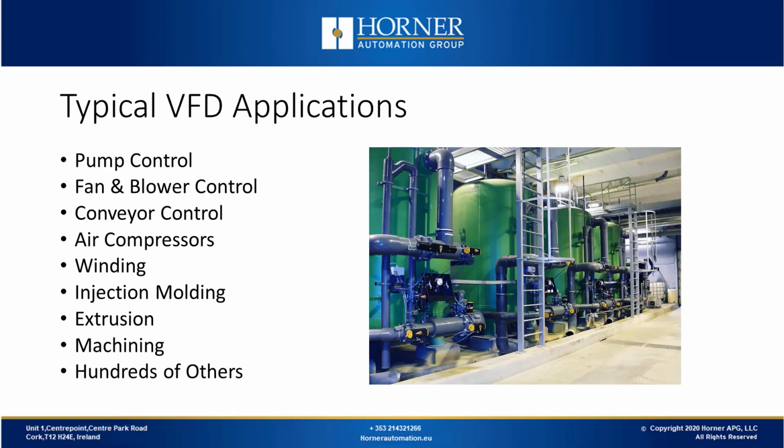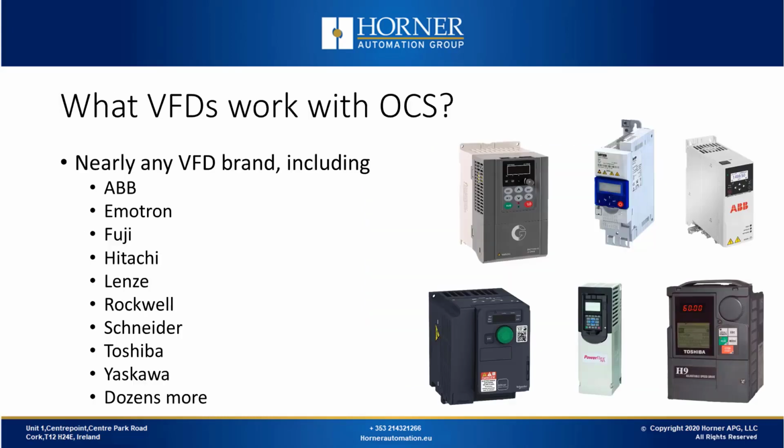Here's a list of applications that you may find VFDs in. Pump control is one of the most popular, fan and blower control, conveyor control for controlling speed, etc., air compressors, winding type applications, in the paper industry, or maybe even the metal industry, injection molding for aluminium, and literally hundreds of other applications as well. It has many uses.